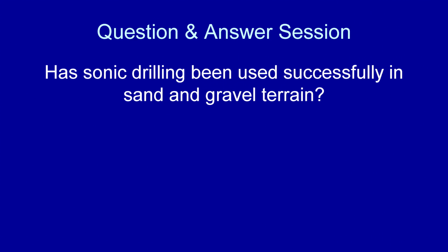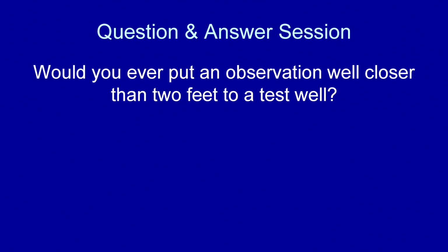Also, in fact, if your static water level is going to be below 24 feet, a sonic rig will allow you to put in a 4 or 6-inch diameter test well that you will then be able to put a submersible pump in and make an accurate evaluation. Great. One other question that we have is, would you ever put